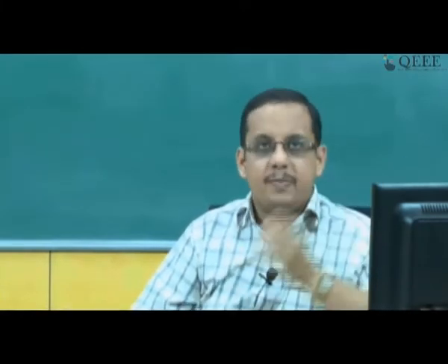For higher velocity ratio, which type of gears are used? SUCET is asking. I think we covered these topics on the first day of the lecture, but nonetheless, since you have asked for a higher velocity ratio, maybe one gear arrangement is the best, but here we are talking only about spur gears. Though it is the simplest possible gear, it has very many applications, and you have seen that the ready application of it was in the context of automobile transmission. Some automobile transmissions will have helical gears, because helical gears, as I said, have smoother operation. But in this course we are talking about spur gears alone.